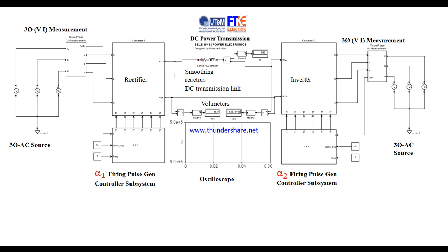The simulation produces a clear concept, implemented in 10 steps. One is to create two asynchronous three-phase AC supply sources, two converters and inverter with the parameters of the resistor and their configuration, connect the DC transmission link between the converter and the inverter, add filters, use smoothing reactors and capacitors, add necessary parameters, and oscilloscopes to see the graph and the waves.